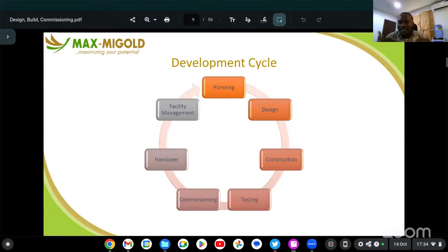All those checks for functionality are what we refer to as testing. And we shouldn't forget that when we do those checks, we should always document the data generated. If I energize the system and check from live and neutral and get 220 volts, I need to document it. There should be a template to document that this particular system, when it was tested at this time by this engineer, this was what we got as the incoming voltage. Each of the components will be itemized in that checklist. Is it okay? Yes, good, not applicable, just like that.